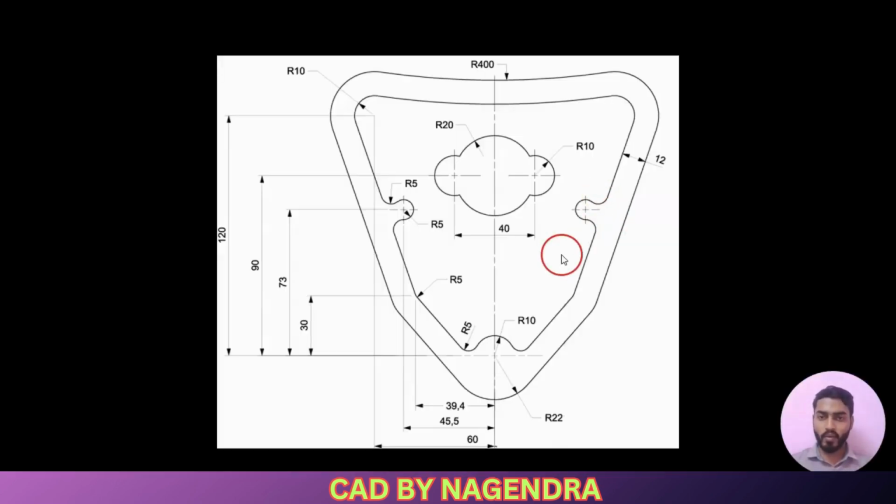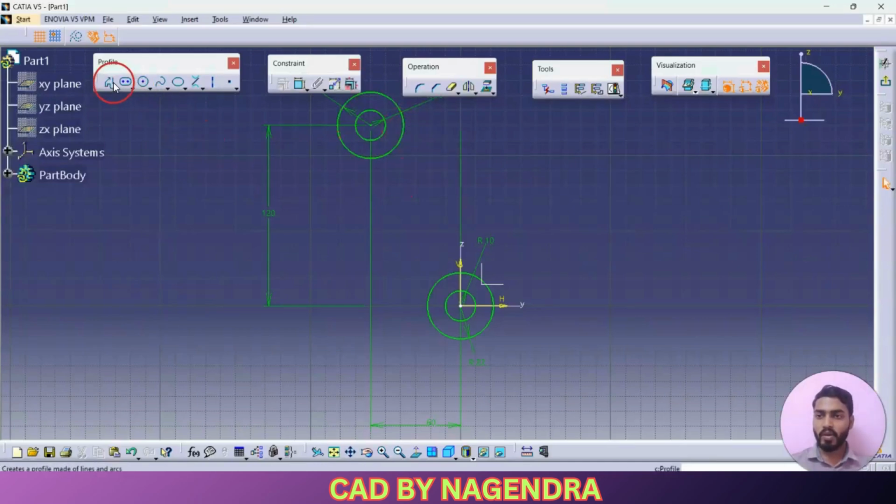Next we need to create this shape. In between these two I am going to create this inside part. Why? Because we have one inclined line up to here and one more inclined line there. We don't have any dimension with reference to this particular point, but as you can see inside, for this particular point we have vertical and horizontal dimension. So first we are going to create this profile like this: just one inclined line and again one inclined line for this inside radius of 10 circle. Now let me use Profile. I'll start somewhere from here, one click up to here, then one click up to here, escape.